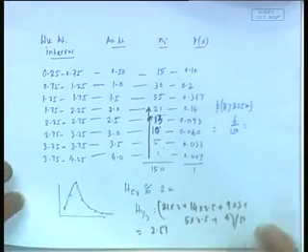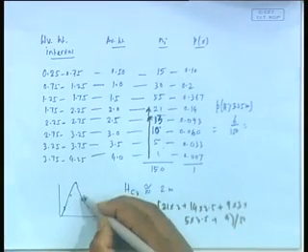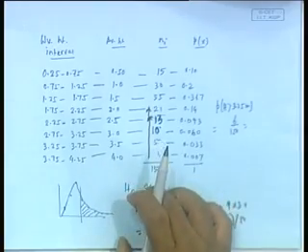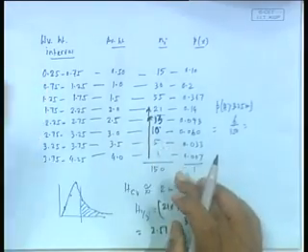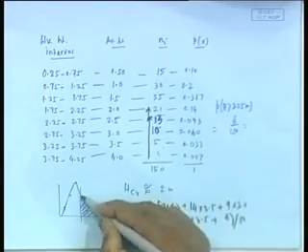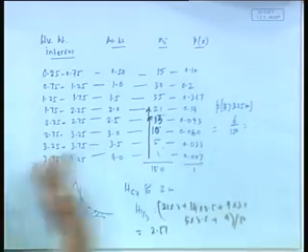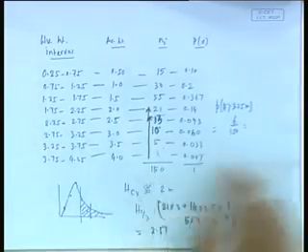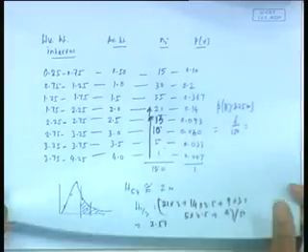So what is happening therefore, if I look at this diagram, it is actually the average of this side, 1/3 of the total number. It is the average of these heights, 1/3 of them from the top side, is H 1/3 height. H 1/10 will be this side. Now this is the concept of significant wave height.